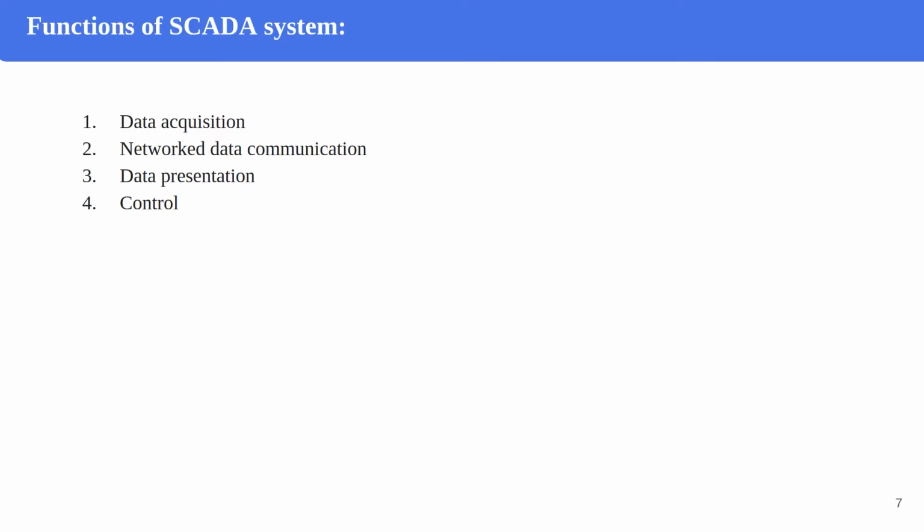They are not able to generate or interpret protocol communication on their own, so we need the RTUs, remote telemetry units, to provide an interface between the sensors and the SCADA network. The RTU encodes sensor inputs into protocol format and forwards them to the SCADA master. And the RTU receives control commands in protocol format from the master and transmits electrical signals to the proper control relays.